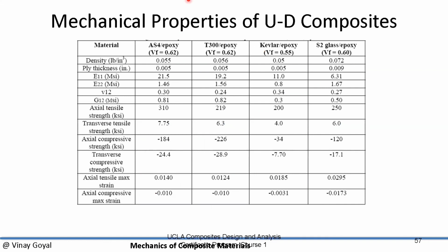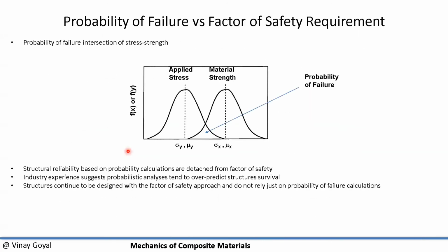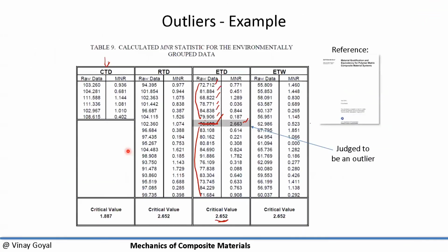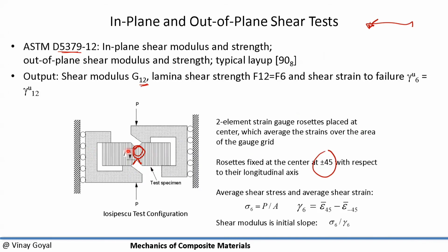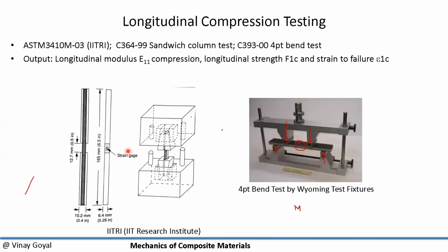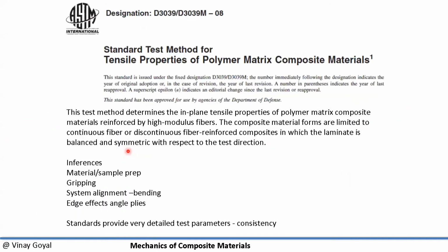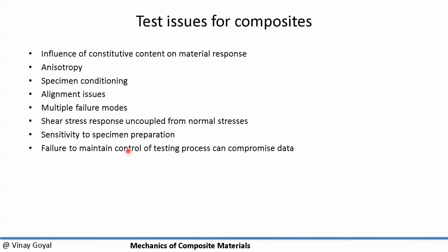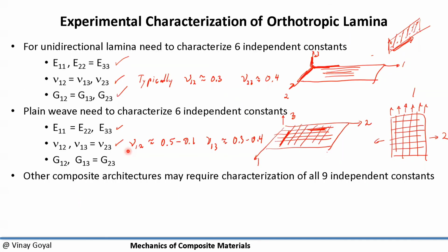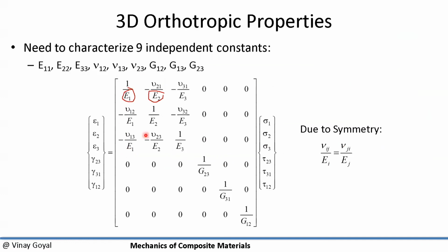So in this lecture, what we've done is learn how to populate the material properties, because we need that for the analysis. We learned how to characterize the material properties using the ASTM standards and how to support that through testing that can then inform this constitutive law equation here. Not only that, you can calculate strength. I showed you that you can actually get strength. You can get strain to failure.